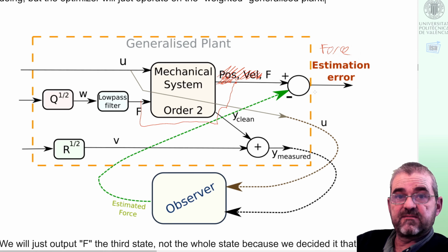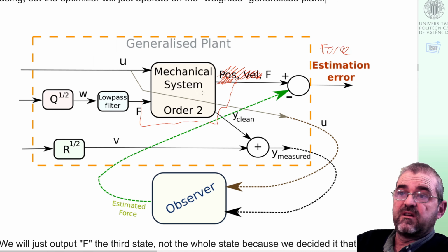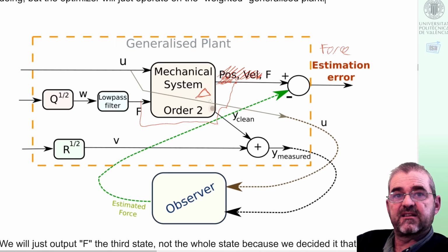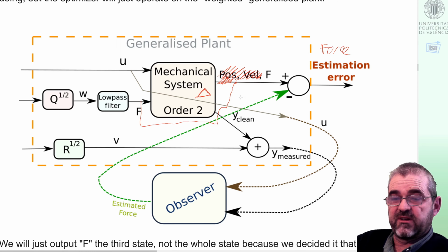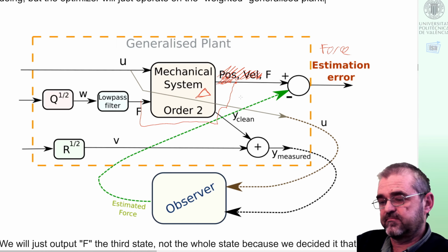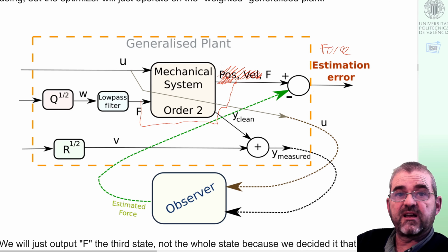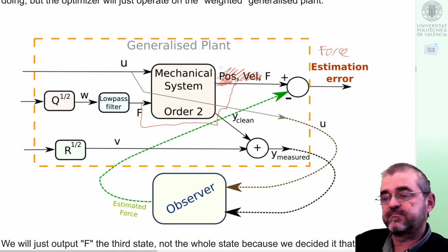Then with suitable weights, if we have here a nominal plant with no uncertainty, we can carry out H2 or H infinity optimization. Or if we have some delta here, we can apply scaled small gain and mu synthesis. We'll do all these options and we'll compare them later on. So this is the block diagram setting we are considering.